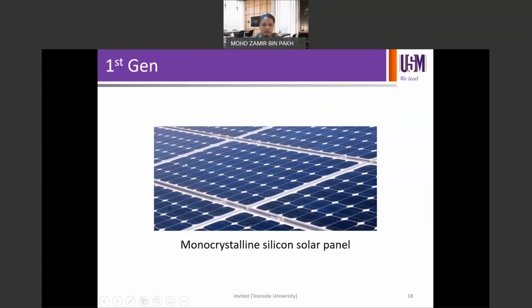So this is an example of monocrystalline silicon solar panels laid on the roof of a building. Normally, one solar panel has 60 or 72 solar cells. If you talk about a 60-cell panel, then normally you can see 5 by 12, which forms the 60-cell panel. On the other hand, a 72-cell panel is normally laid out in the form of 12 by 6. Okay.